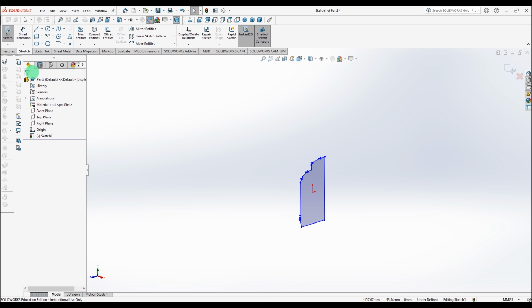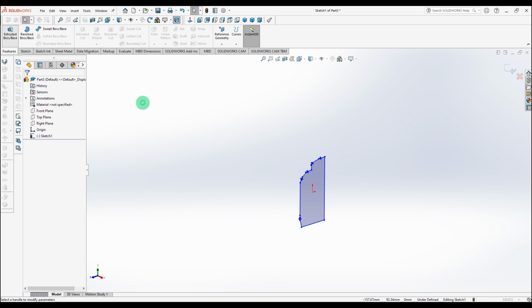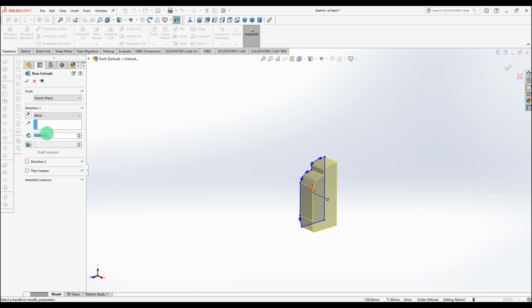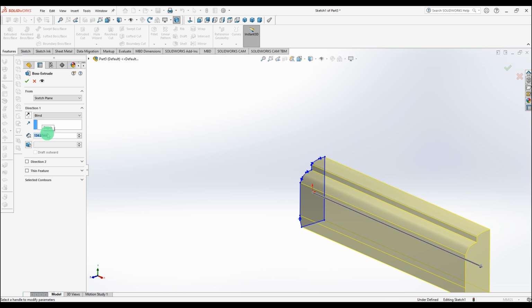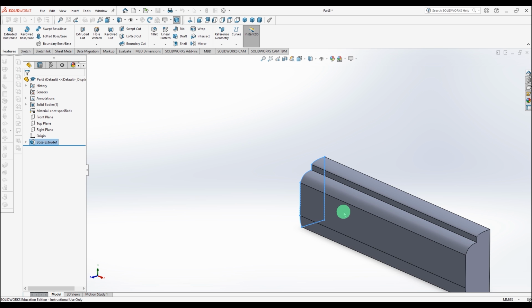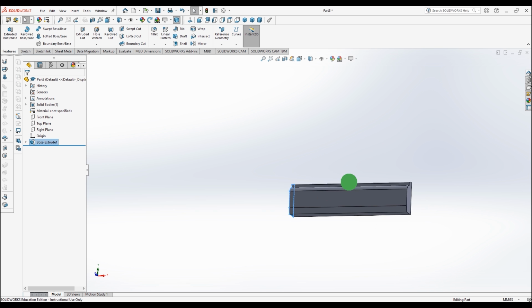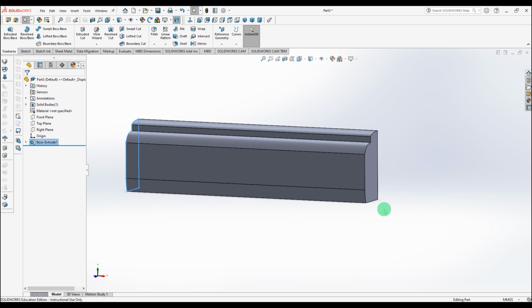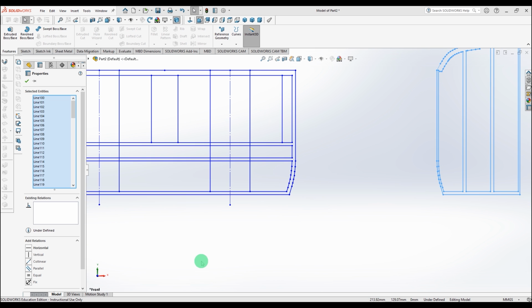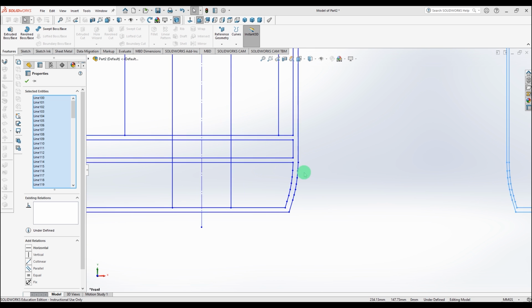Okay, so that'll do for now. What we can do is now extrude that and give it some length. In this case, I'd measured it previously, it's 134 millimeters. So there we go, we type that in and we've got ourselves half a coach body, except we haven't got that turn under or tumble home on the ends.